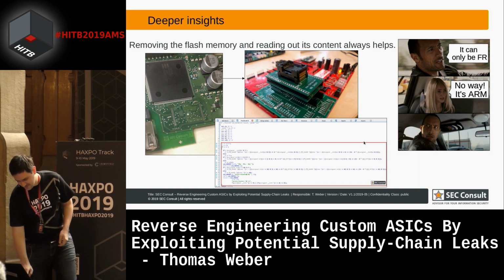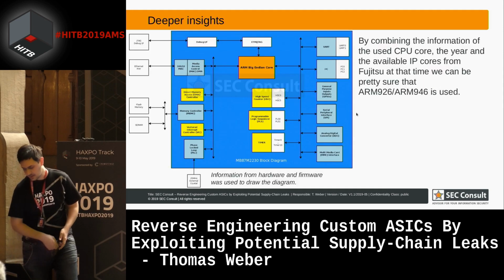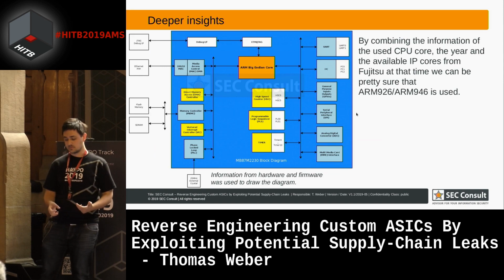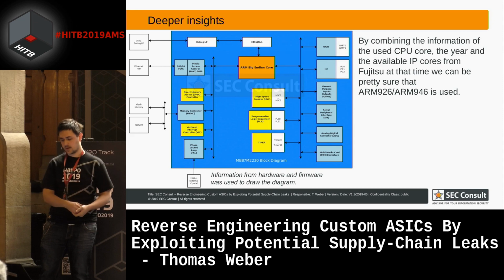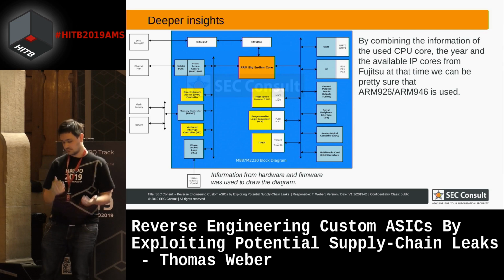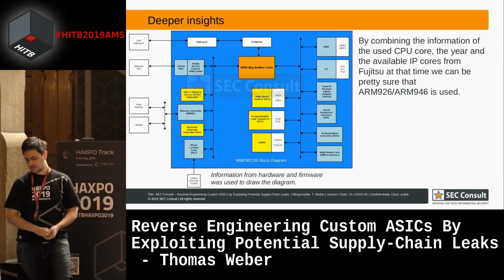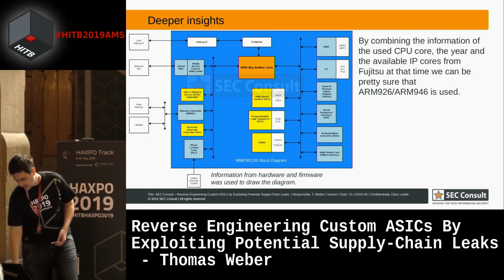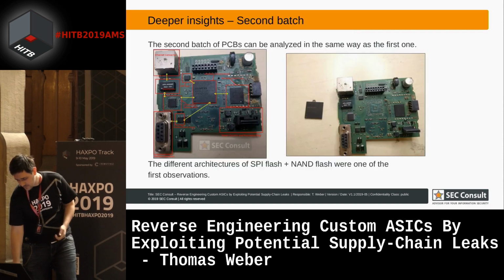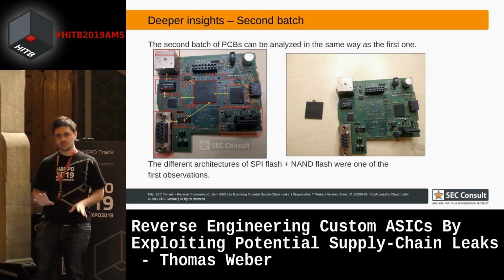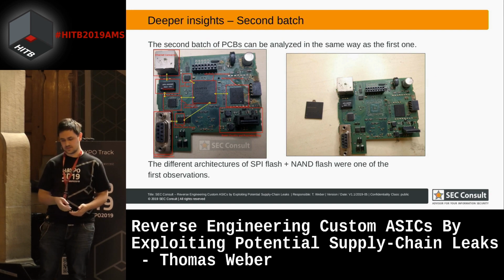And I also got some strings out there which get referenced in IDA, and then I was able to draw some kind of schematic, some kind of diagram. Where is the core? Where are the modules? Which modules are embedded into this firmware? And that was really cool. I also identified that it may be ARM926 or 946, but I was not really sure because of the instruction set. You cannot say it all the time.